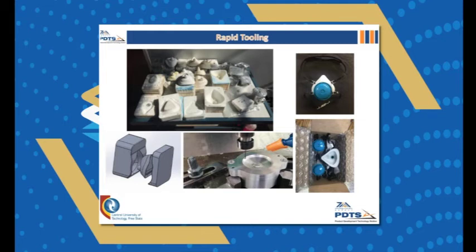To the right of these pictures is the final product, and that is actually the mask which was delivered to the Department of Health and which were used by the frontline workers. It should be mentioned that the quantity required by the Department of Health did not exceed the lifetime of the mold. Otherwise, this would have been another picture. We would have done 14 iterations of the rapid tool, trialed the product, and then create a steel tool which we can then use for mass production of these masks. Luckily, this was not necessary, and we could only use our nylon molds to create this product.